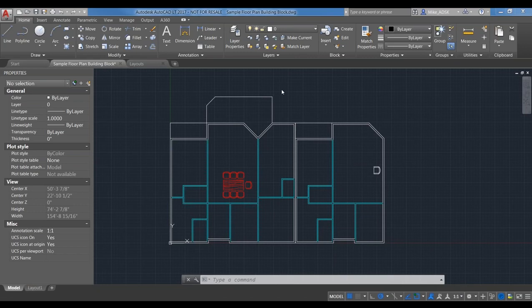A layout itself represents a drawing sheet. It typically includes a drawing border and title block, one or more layout viewports that display views of your actual model space, general notes, labels, and possibly dimensions. They could also include tables, schedules, standards, etc. Usually a drawing file, such as this one, contains a couple of layouts, but you can actually have as many layouts as you need.